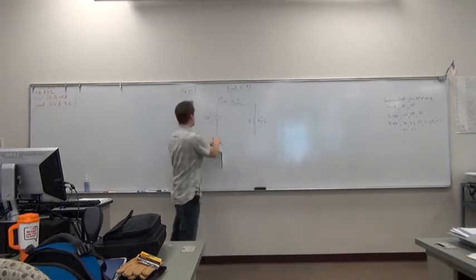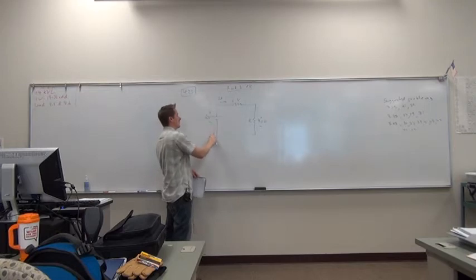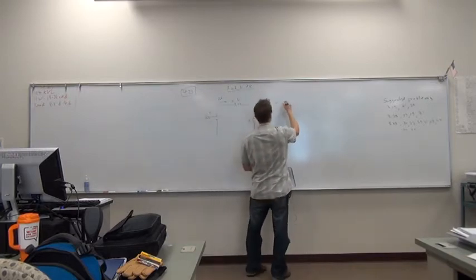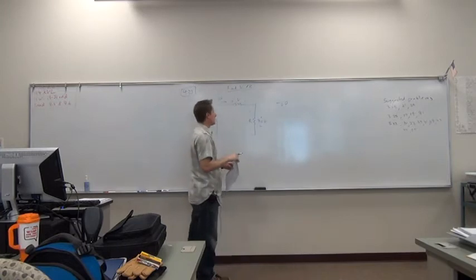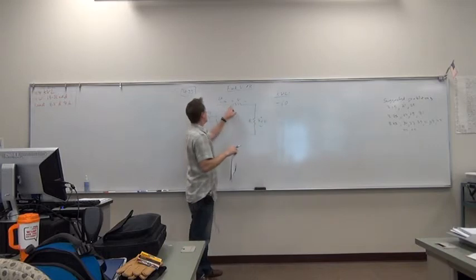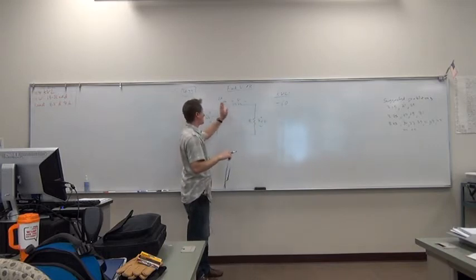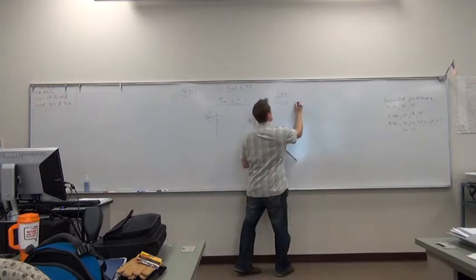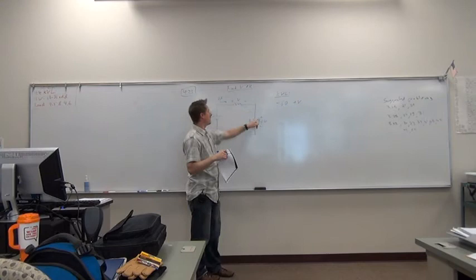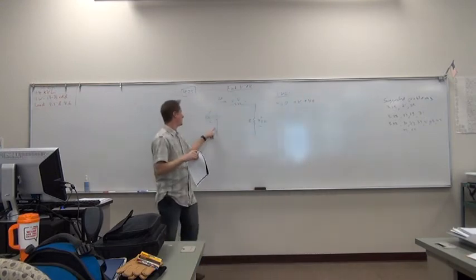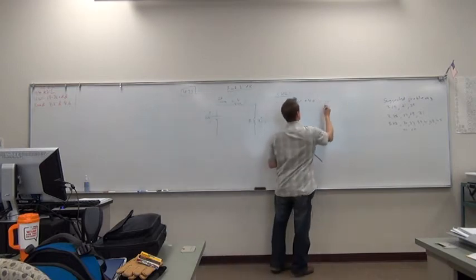So we start at the bottom left corner is what I usually do, or at the negative terminal of the battery. Go through the voltage source, and you see the negative sign first. So you put negative 60 volts to start off with your KVL equation. And then you come through here. You don't really need to know the amps. It's not going to bother you. You're going to hit plus V. You continue to go around, you hit plus 40. You continue to go around until you get to this point, and then you say equals 0.